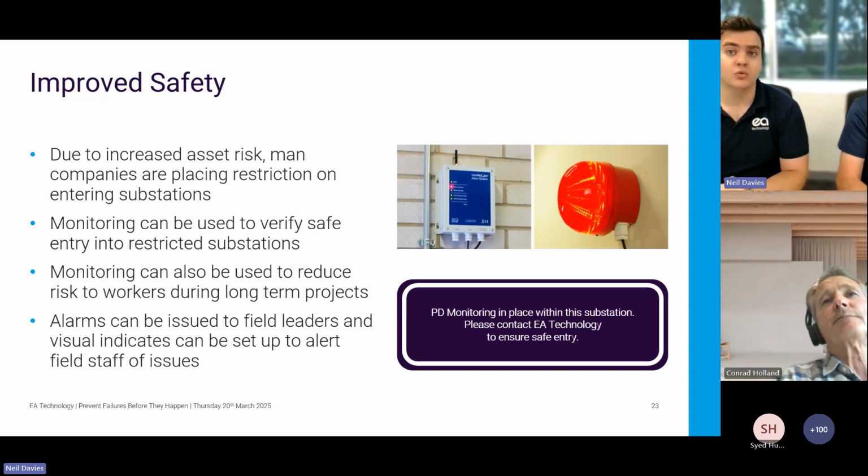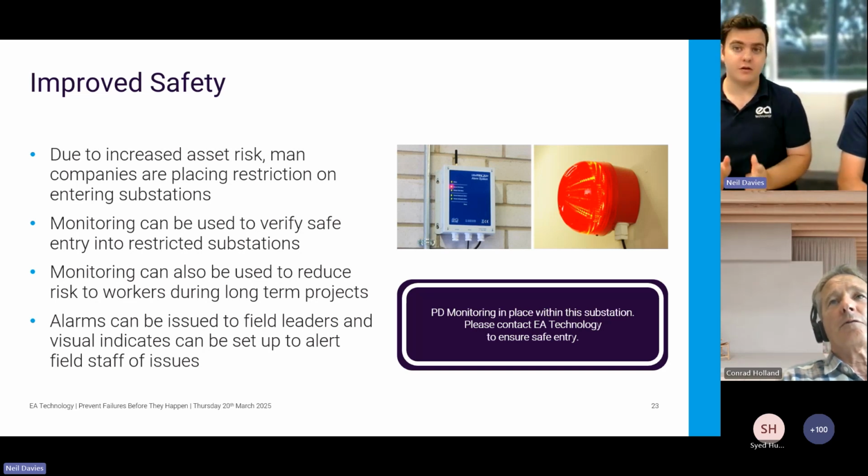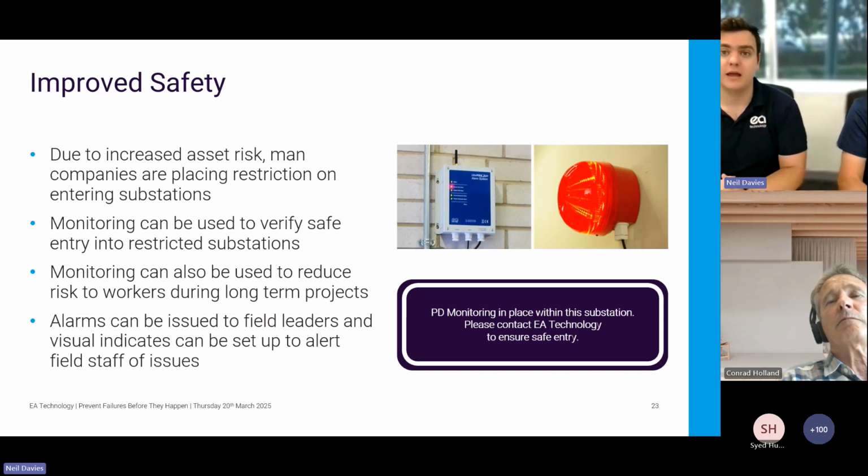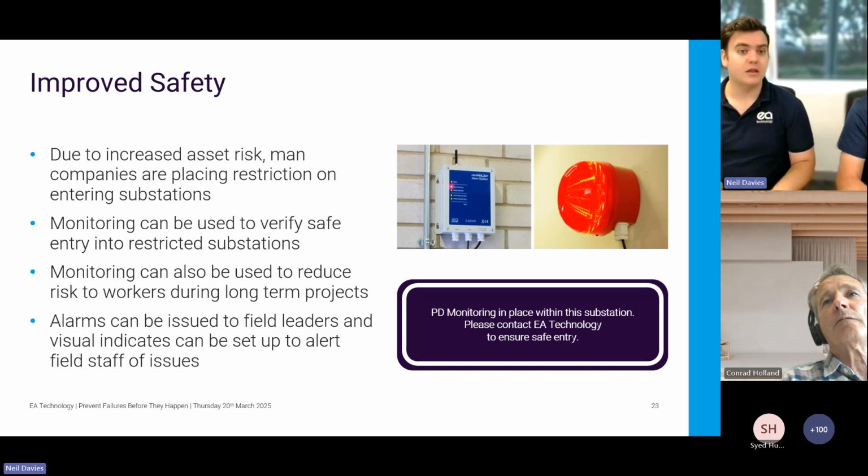And that was a really good initiative put forward, because their biggest concern with the alarms going to the control room or anything like that, if you do have that very small P to F interval scenario, albeit rare, is that the people that need to know are the ones standing in the room with the switchgear and with the potential defects. So this is something that is cropping up more and more, especially on the aging assets.